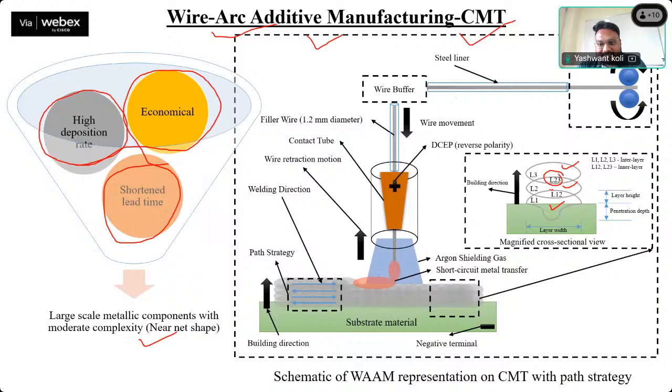This interlayer concept is important because with different materials we form different microstructures in these interlayers. So L1, L2 are the layers that we are depositing, and L1-2 is the interlayer formed during the combination of the two layers. So this is also known as the heat affected zone. You can call it the heat affected zone, and it's the weakest zone.